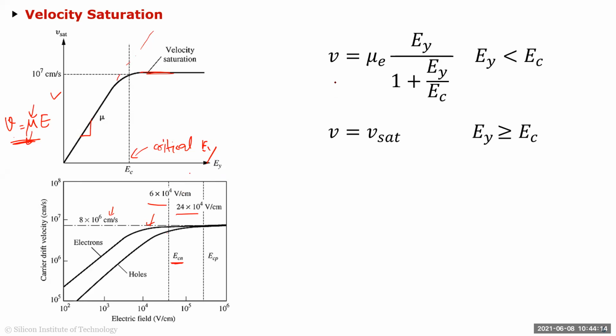And to give you a first order modeling of this so that you can use it somewhat in your hand calculation, this is modeled as a piecewise linear. So you have this piecewise linear where you basically use the mobility equation like you do for low fields here. So this is a piecewise linear equation where for low fields, it asymptotically equates to here. For high fields, it becomes constant, it becomes VSAT. So it asymptotically joins to VSAT. So this equation does a piecewise linear for that.